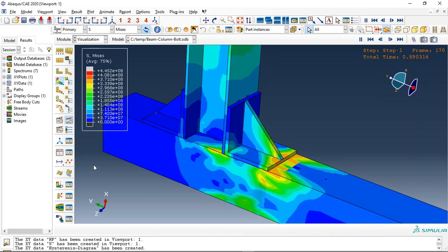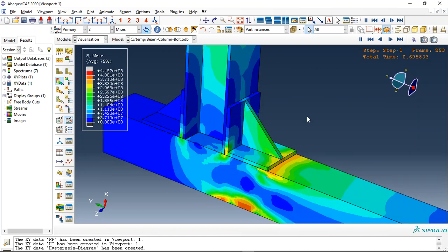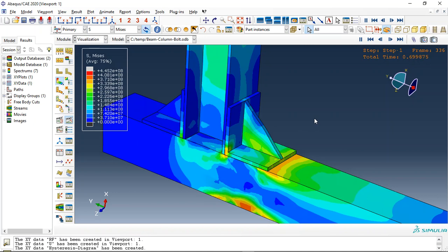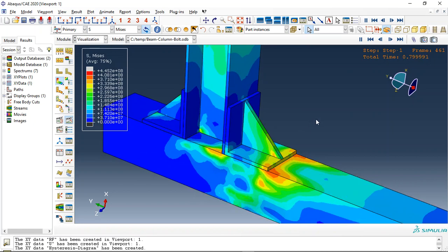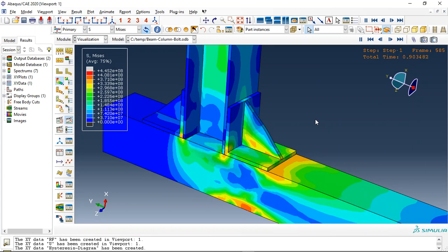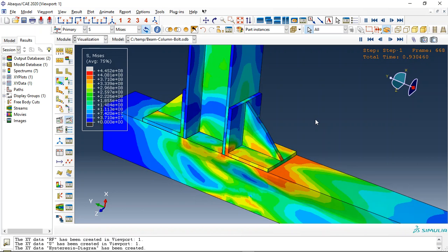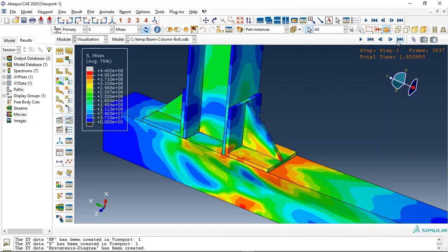Now I'm going to draw the hysteresis diagram, which is the force displacement under this cyclic loading, and we use the hardening which is appropriate for cyclic loading, because in the cyclic loading we have changing in the yield surface, and in each cycle the stress strain remains in the material, and the Abaqus should consider that residual strain stress. So we should use a specific type of the hardening for the steel material. Okay, and this is the final frame.